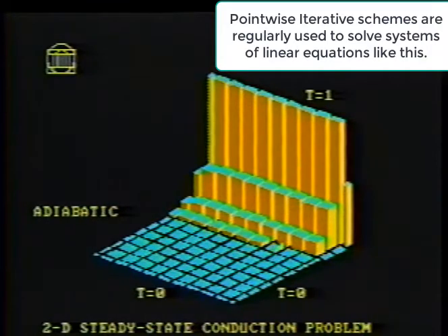We're using an iterative technique to solve the equations in this case, something called Gauss-Seidel Iteration. And you can see that we're sweeping our way across the mesh and plotting at each node on this mesh a bar that's proportional in height to the temperature of that cell.